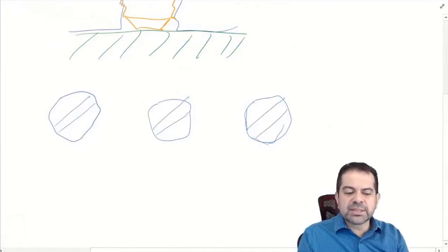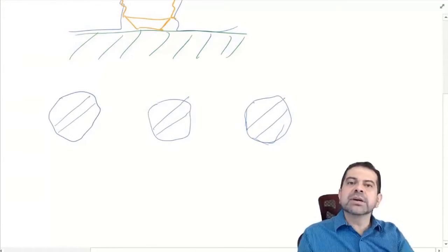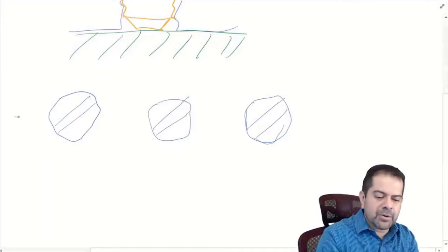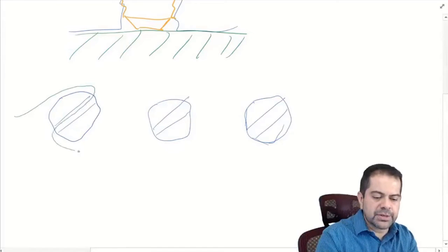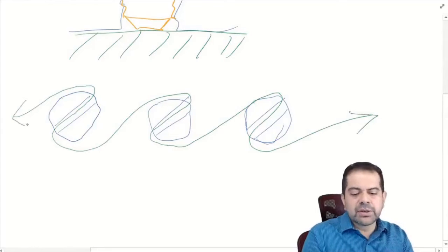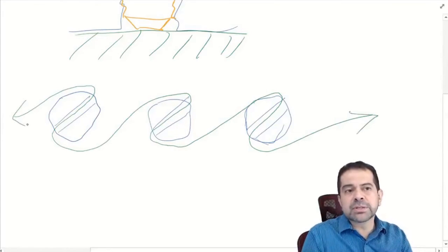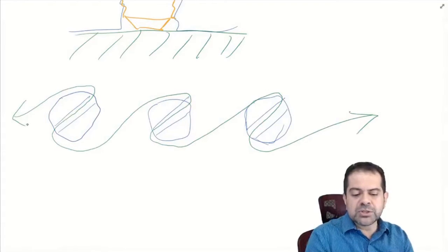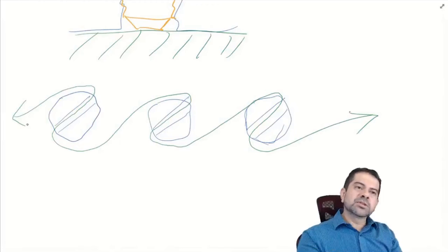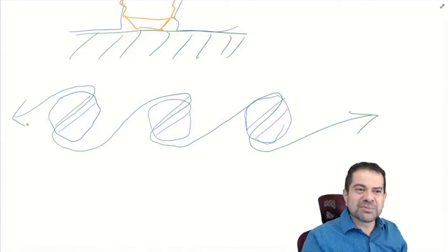or remove these screws, we would go counterclockwise. So we need to apply this metallic wire in a way that it keeps counterclockwise rotation. So in this case, it would probably be something like this. If we route it this way, you can see that with tension on this wire, the more you apply tension, the more counterclockwise they're going to go. If a screw wants to back out, and, did I do it the other way? So sorry, I did it backwards. This would be the way not to do it. This is if you want them all to back out at the same time.